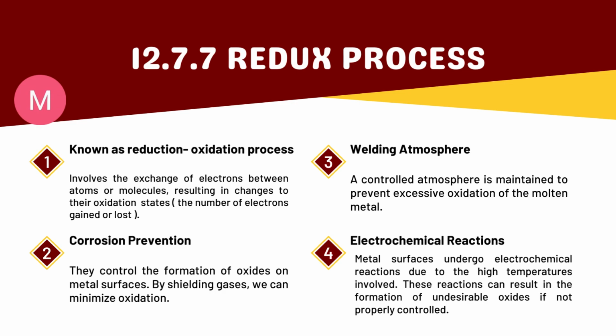Third, welding atmosphere. A controlled atmosphere is maintained to prevent excessive oxidation of the molten metal. Electrochemical reactions. Metal surfaces undergo electrochemical reactions due to the high temperatures involved. These reactions can result in the formation of undesirable oxides if not properly controlled.